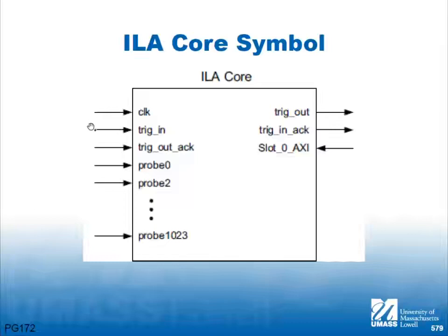This is where the power of HDLs come in. So if you need a very specific trigger, you need a trigger that does some state analysis before it triggers. So it looks at previous events, it sets timers, all the stuff that was in that awkward GUI menu, you can build logic here in VHDL or Verilog that's going to generate that trigger. So now using the tool that you already have, you can build very complicated triggers.